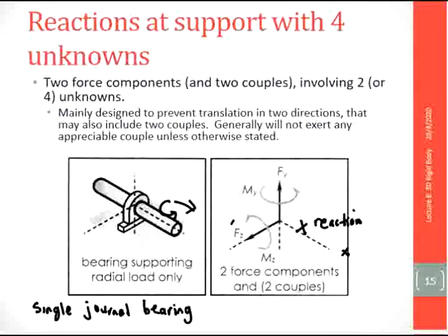So that's why we have Az here and Ay here. And this structure also cannot rotate about the Z and Y axes. So that's why we have the other reactions, moment Z and moment Y.